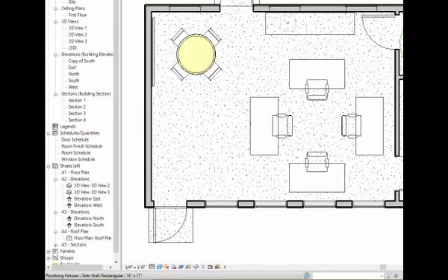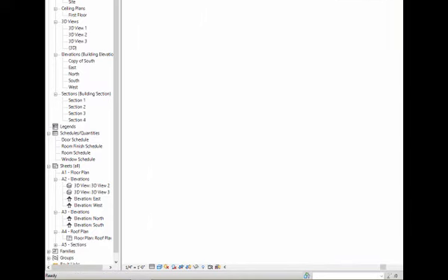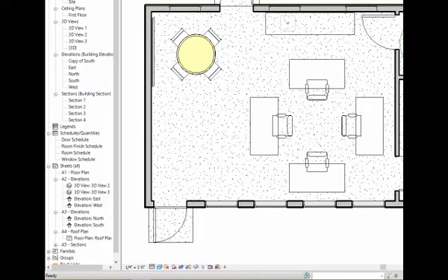So where I was going was to show you that the sink, which is located in the bathroom area, is currently over towards the left-hand side of the room. If I move it over to the right-hand side of the room, closer to the toilet, you'll see that it's moved here in the floor plan view, but it's also moved in the furniture plan view.